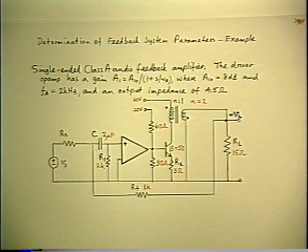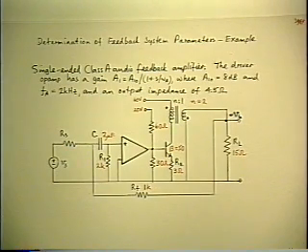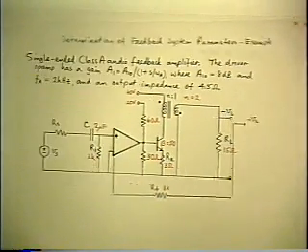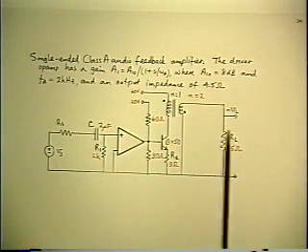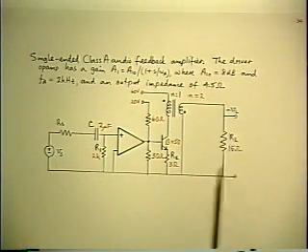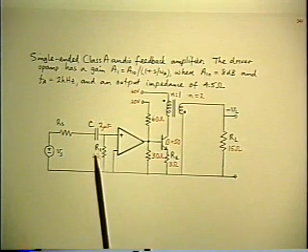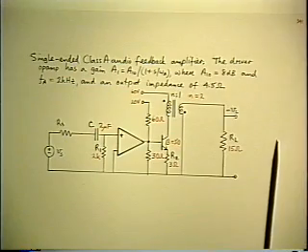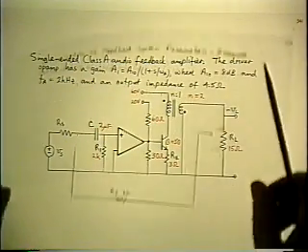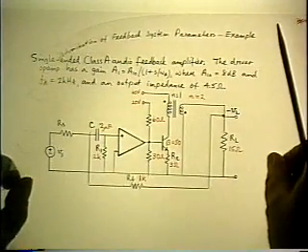Now again, to revert to the conventional analysis, just to illustrate why you run into difficulties, the conventional approach would be to break the feedback path, calculate the forward gain, and then put it back into the closed loop. And the trouble with that is you get the wrong answer, because you've changed the value of A by taking away the feedback path.